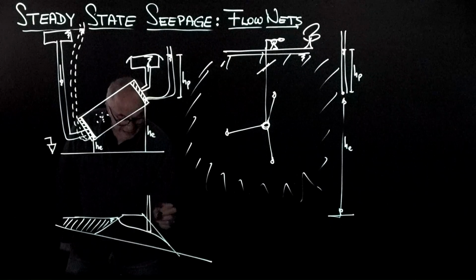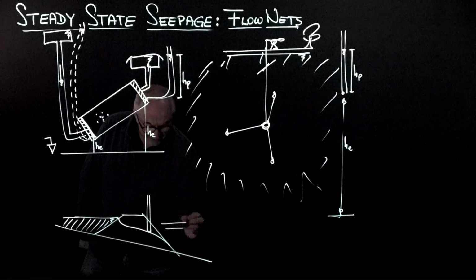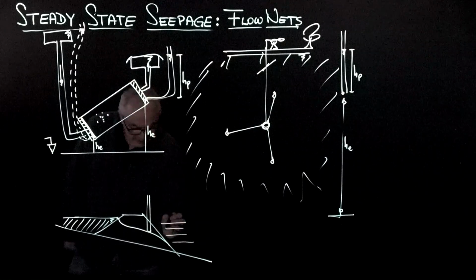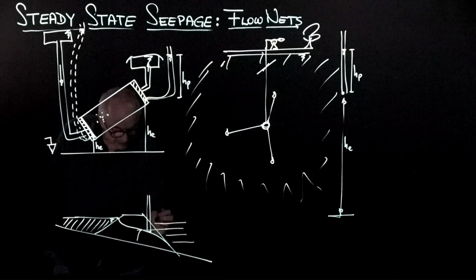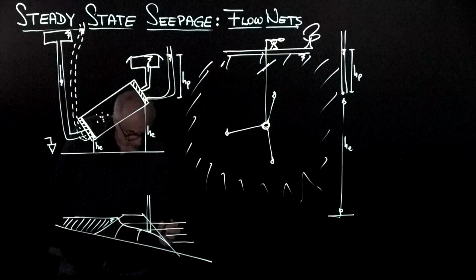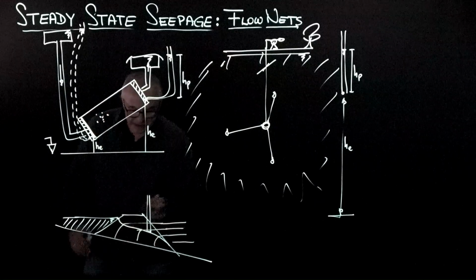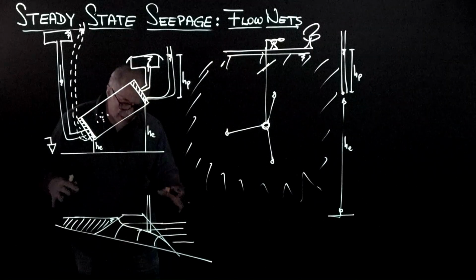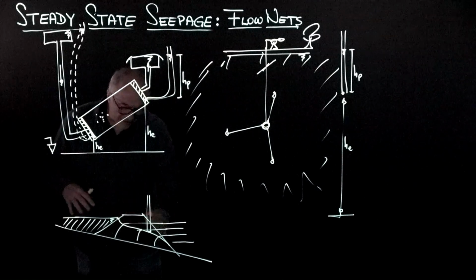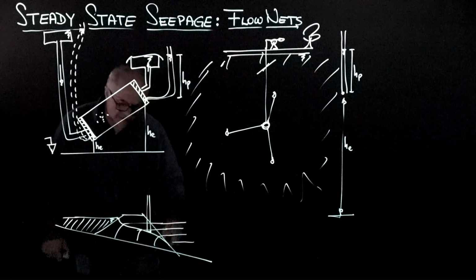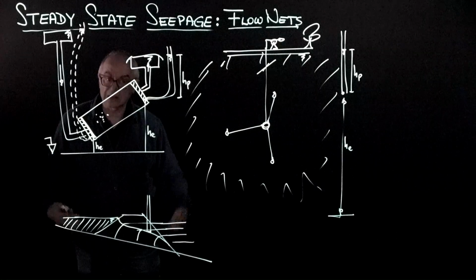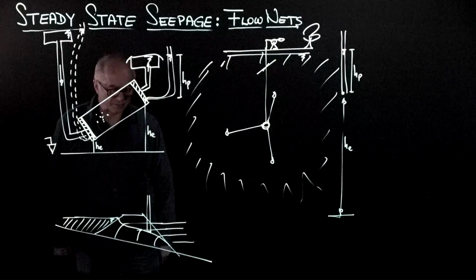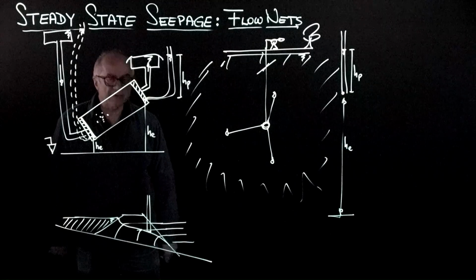Therefore, I can identify at different elevations, I can go and intercept, and there will be one equipotential that will come here, one equipotential here, another one here, and so the flow net will evolve to adjust the phreatic surface to make the whole system self-consistent with the boundary conditions while solving Laplace's equation. In summary,